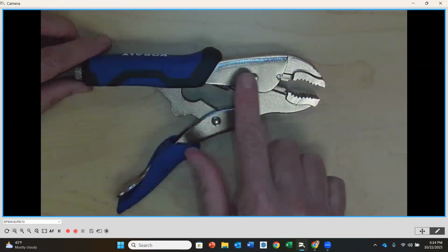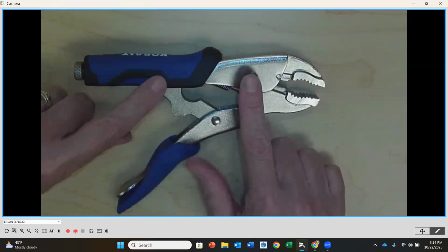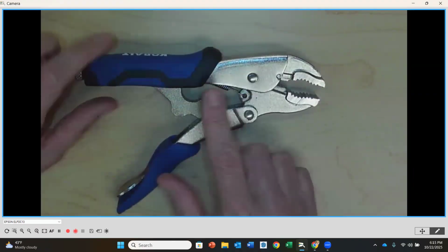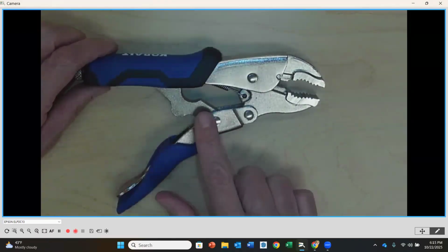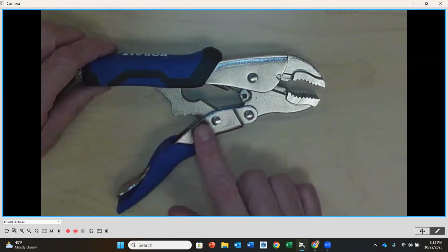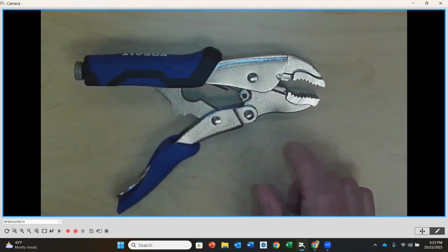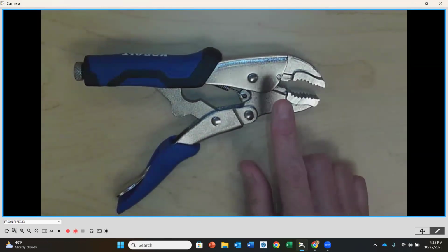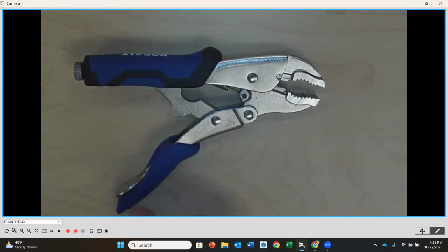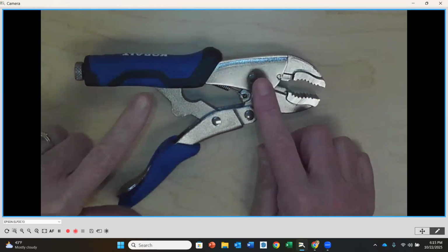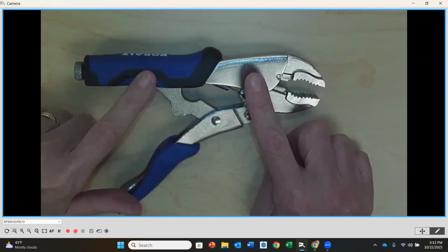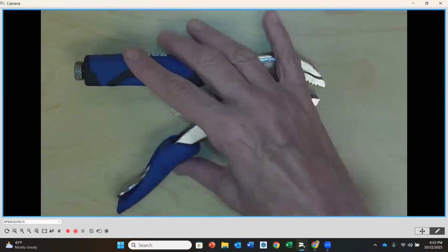So what we have is our frame. There are two connections to the frame. There's the connecting rod here, to the handle, and then to the jaw. Okay. So let's go through the process of drawing the kinematic diagram for this. Starting with the frame members, there are two frame members right here, and they're about in line with one another.